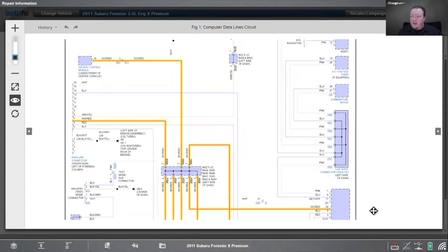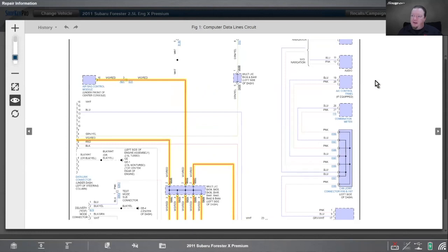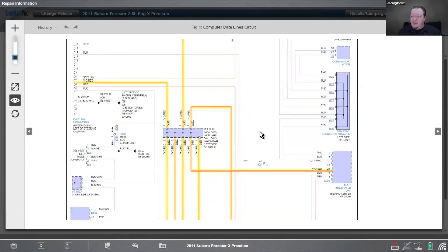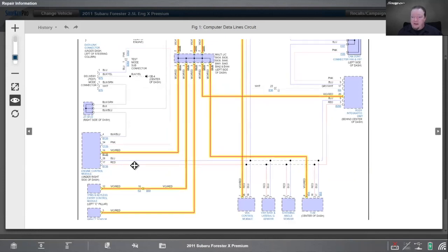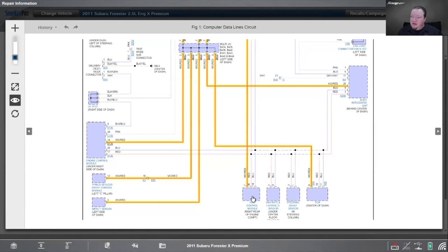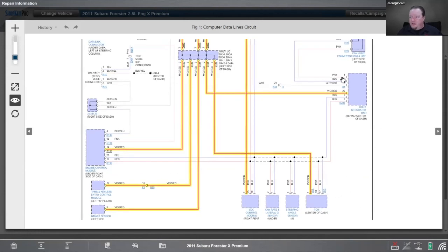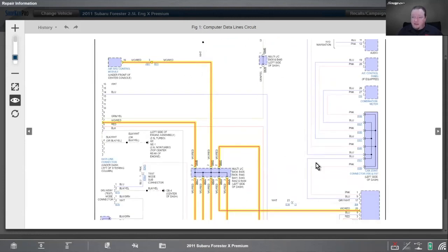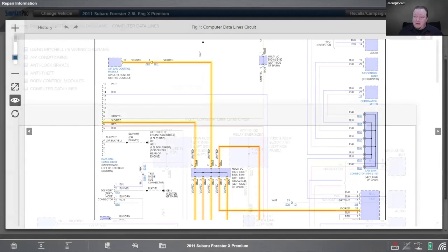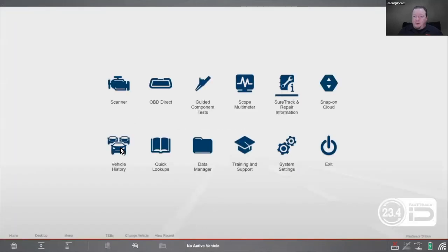the body control module. And then from the body control module, if I need to communicate with anything else, that's going to be over CAN. So it's going to depend on what module needs to communicate as to whether or not it goes over CAN or over that K line. We can see it's just the main modules, right? So ECM, TPMS, impact sensor, vehicle dynamics control, transmission, body, and then up here is the airbag. So all the major modules on the vehicle can be accessed through that one line, and then everything else is on the CAN bus. So you've got to kind of get used to reading through wiring diagrams in order to get here. All right, let's go to 2 more examples on the diagram.